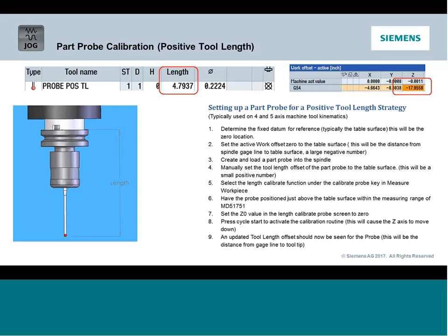But the basics of how you would calibrate it is first, you're going to give the machine a rough tool length of the tool probe. So here it would be a distance from gauge line to tool tip. You can do it with a tape measure. You can come down to a piece of paper, just get a rough dimension. You want to have that dimension in initially. As well, you would have put the diameter in and probably already run it through the diameter calibration.